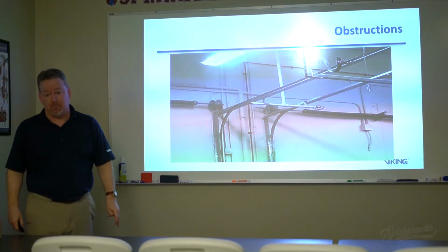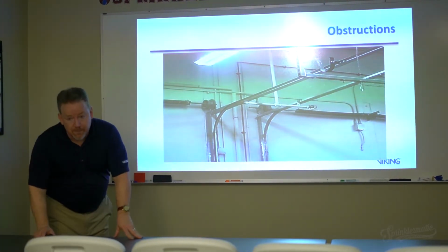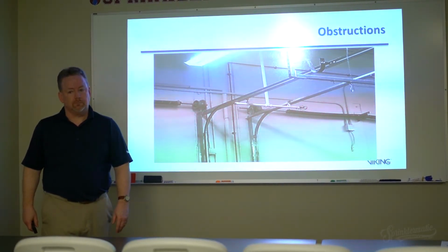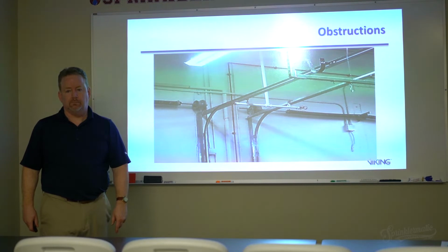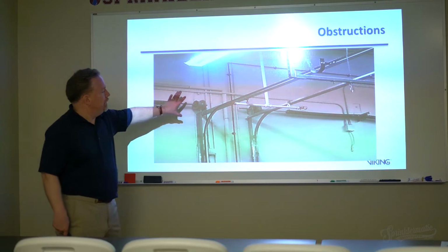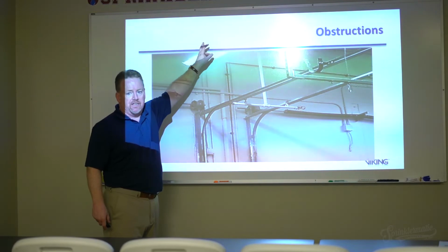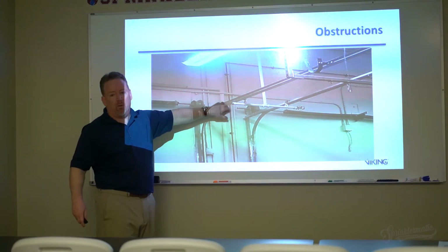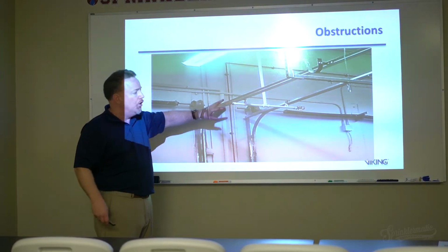False ceiling basically is what you've opened up to, because most doors are 8 to 10 foot wide. My question is that the branch line is you can have it closer. It's going to work when the door is open below. But I'm saying your distance doesn't matter. No, because if these are closed, what sprinklers are going to provide the protection? The ceiling sprinklers will, and we're not even going to rely on these to do it. It doesn't matter if these get wet from the other sprinklers because we're not relying on these to operate in that case. Okay, only when the doors are open.